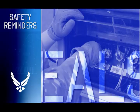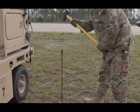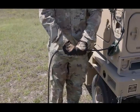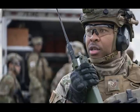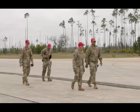Safety reminders. Let's review some critical safety reminders. Always ground generators properly. Check all connections before powering up, and use the correct personal protective equipment, including gloves and eye protection. Communicate clearly via radio during installation and ensure all hazards are mitigated before beginning work.